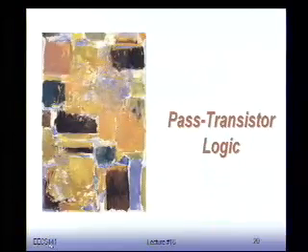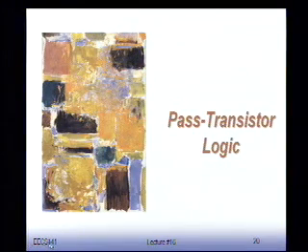All right, that's that. Now, an interesting logic family, but of limited usage. I said the static power dissipation becomes an issue. And you can also imagine that if I have to do differential logic, that's going to be a nightmare from a wiring perspective. You double the number of wires. Otherwise I have A, B, C. Now I have A bar, B bar, C bar. They all have to be wired and connected. You get a rat's nest, and typically it pushes the logic a little bit apart. All right. Let's go to something different.